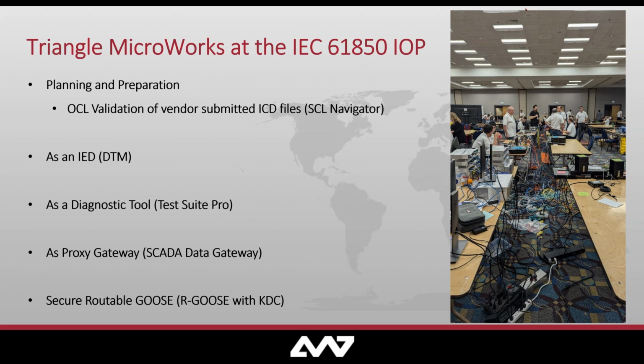So once these ICDs were submitted, one of the ones that we submitted was used in DTM, as I mentioned, to emulate an IED that would participate in the functional tests that would happen later on in the week. Test Suite Pro was involved as a diagnostic and monitoring tool. Its role was to validate the performance of other IEDs during the functional tests and ensure that they were operating as intended. To do this, we would collect GOOSE messages as well as reports from all the devices participating in the test, and then compare those captured messages to the expected results.